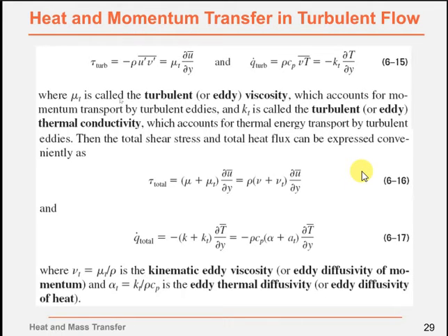And here we call the viscosity in turbulent flow, mu_t, the turbulent viscosity, or eddy viscosity. And we call k_t, the conduction heat transfer coefficient in turbulent flow, the turbulent thermal conductivity or eddy thermal conductivity. So it is different from the mu of the fluid and the thermal conductivity of the material.